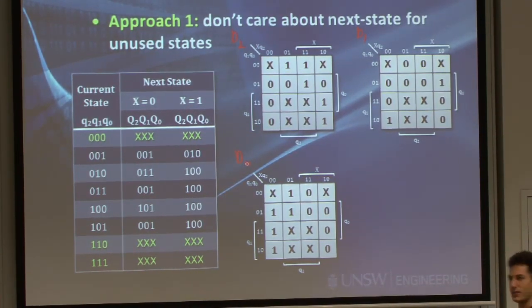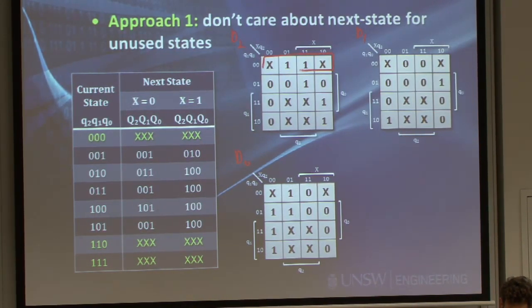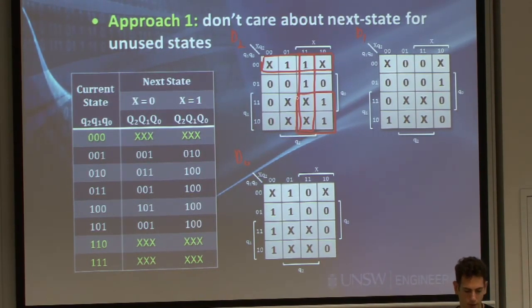And as you can see, I've done you a favor, and I'm not filling up the K-maps anymore. But I will try to group them together. Trying to group these, and if someone can see a better grouping than what I'm seeing now, please do tell me. I can probably group these, and I am utilizing the don't care. These ones? Anything better than this?